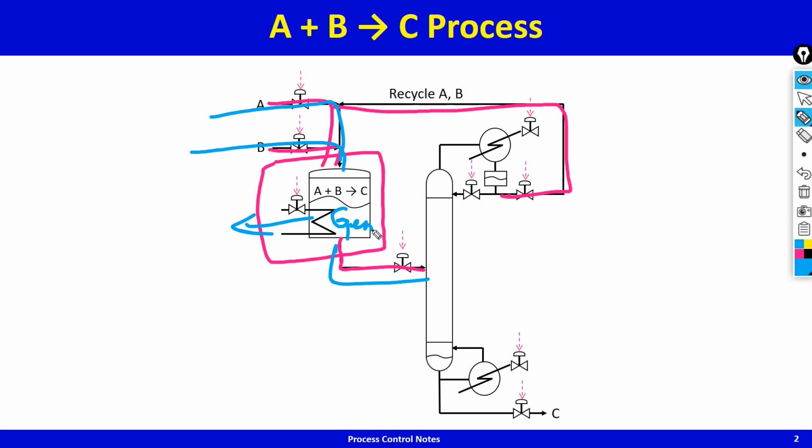You look at any unit and you'll see that with this kind of a running scheme where you're just allowing the operator to directly set the valve positions, there's going to be a lot of trouble, because none of the balances are automatically closed, and because they are not automatically closed, the operator will go mad moving this valve, that valve, to keep this level, that level, this temperature, that pressure fixed, to not allow a drift in these entities.